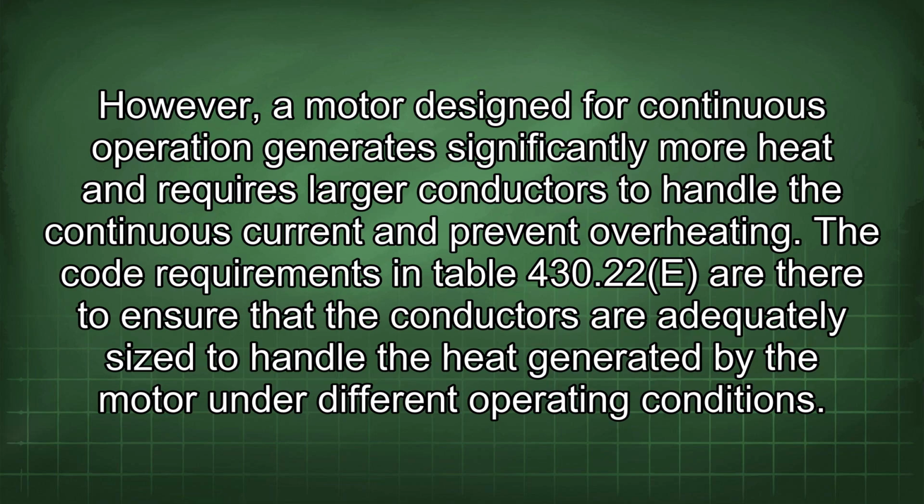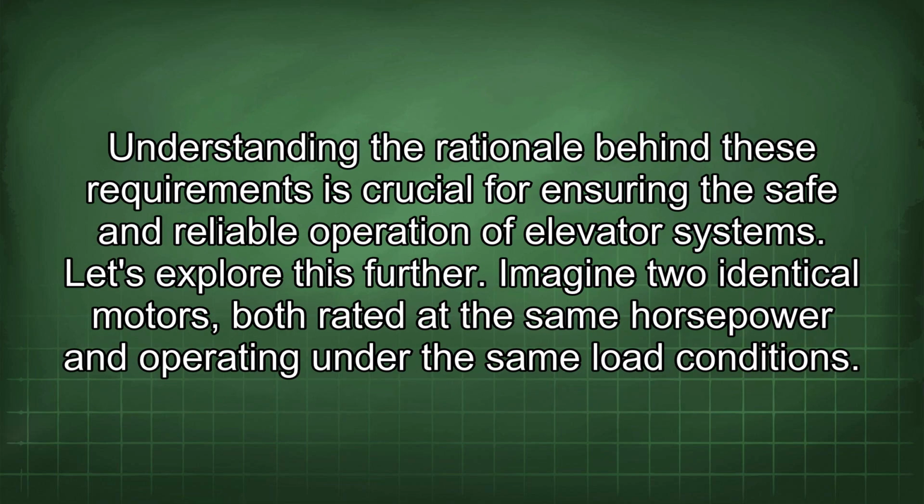The code requirements in Table 430.22(E) are there to ensure that the conductors are adequately sized to handle the heat generated by the motor under different operating conditions. Understanding the rationale behind these requirements is crucial for ensuring the safe and reliable operation of elevator systems. Let's explore this further.